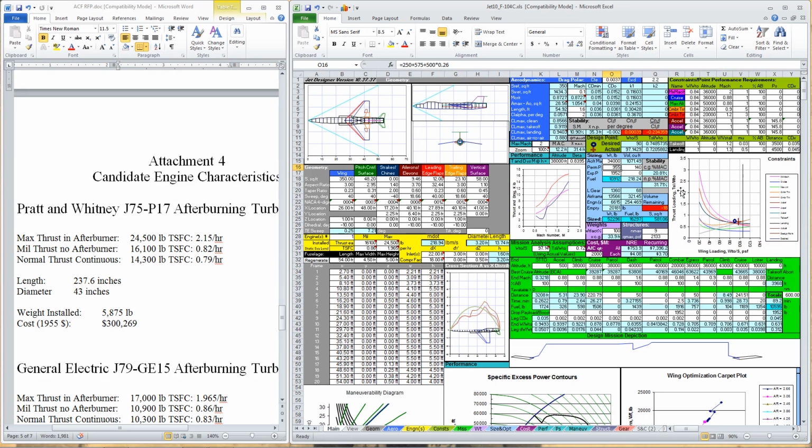And the only thing we need is a little space. We've got a pretty good design here. We could use a little more wing area to get the extra space. Let's try 400. We can put fuel in the wings. And there we are again. Now we're just a couple hundred pounds. Let's try 34,400. And 400 pounds of gas take up 8 cubic feet, and that's exactly where we are. We can go 34,300 and only need 6 cubic feet.